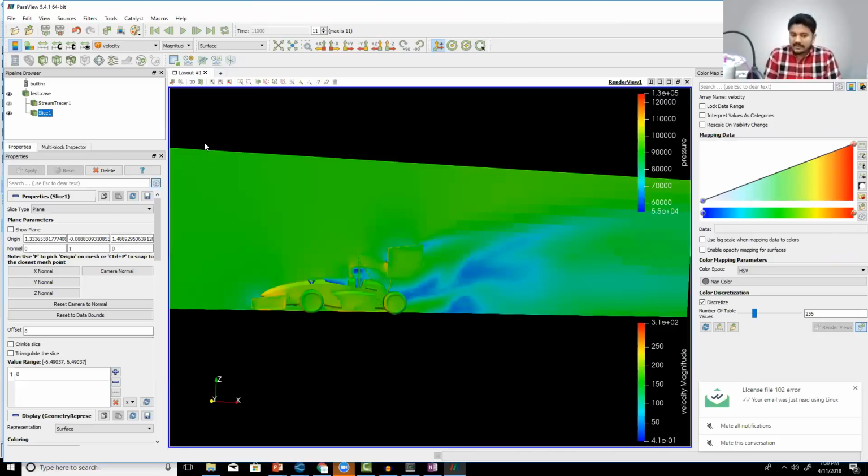So in this particular case, since this is just a proof of concept, meaning we really don't have any type of experimental data on this particular model, the easiest thing that you can do that makes the most sense is to set the yaw angle to 0 and run the simulation on it. And that's what we are doing. Does it make sense?